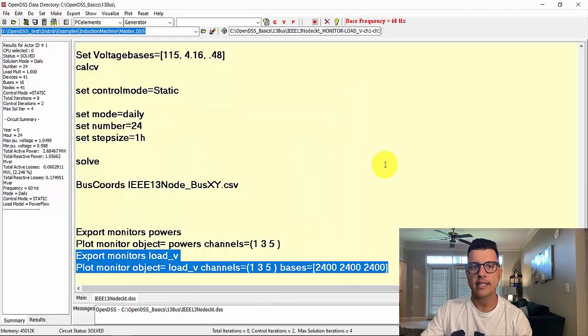So guys, that's what I wanted to show you regarding the results. I just showed you that you can get results from your energy meter, which is basically energy, max power, those type of things. And here I showed you how you can get the monitor results, which is basically electrical quantities over time for a specific point. Okay, very important to mention again, the summary and most of those results, those reports, are for the last hour you have simulated or for the last time step. So important not to be confused on this.